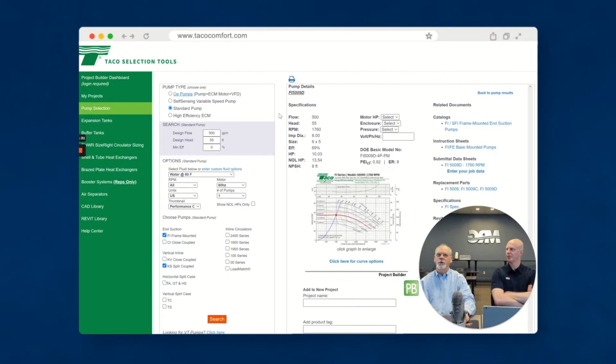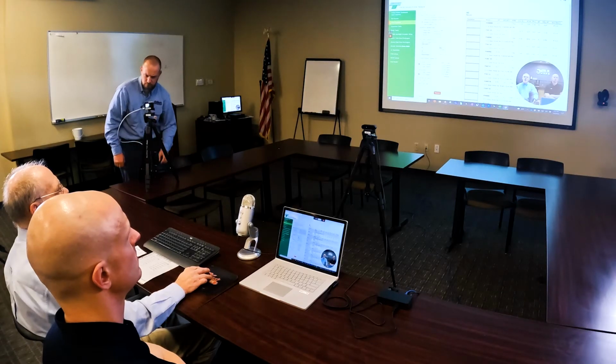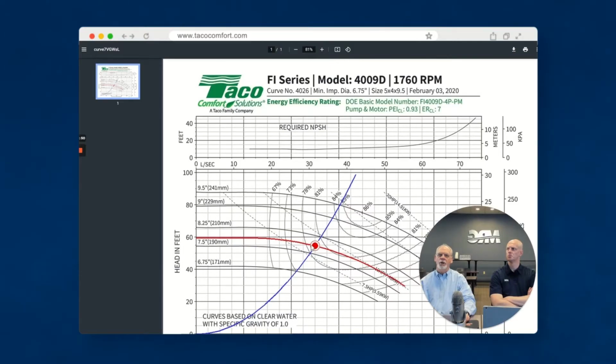We go back to our camera. Just turn it back on. We go back to our chart and get back to our selections. The pump that we want to look at is the 4009 pump, and if I look here, it's still close to this sweet spot. A lot of folks like to stay on the left of center. That doesn't bother me too much. The reason I want to stay on the left of center is we're going down towards our horsepower line.